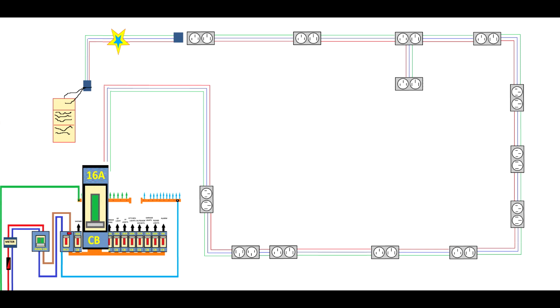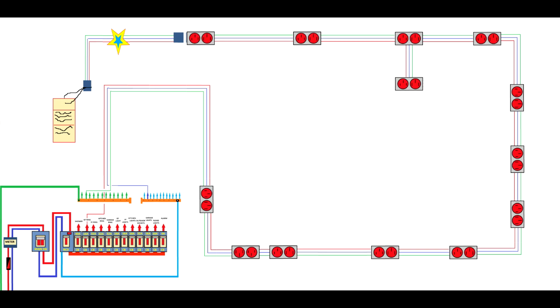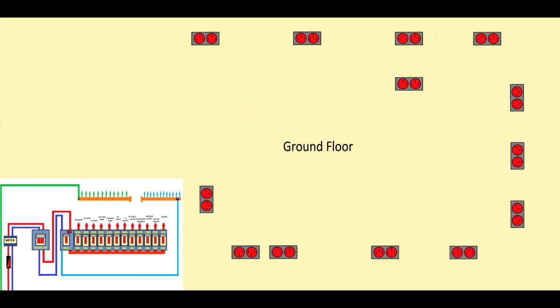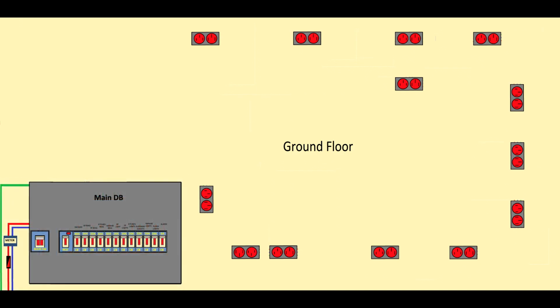You will change the circuit breaker and put in a 16 amp circuit breaker, and you'll tell the customer they don't have the same power as before because part of the circuit is broken, and in that case you have to come back, break the wall, change the wire, whatever. If you leave the circuit running, obviously the customer knows he cannot use heavy-duty appliances like microwaves combined with washing machines, fridges, toasters, etc. So this is it about the ring circuit.